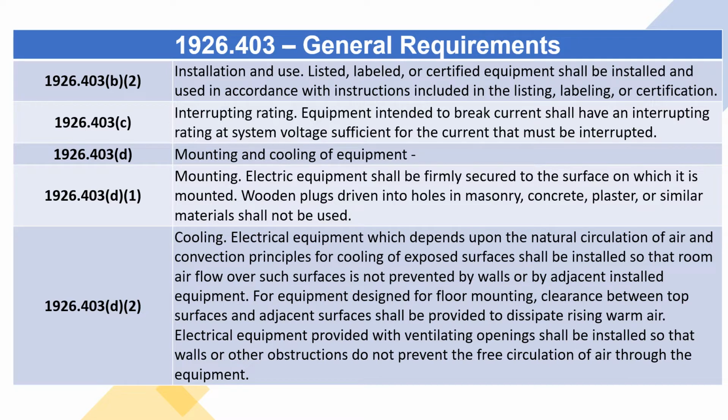1926.403(d) Mounting and cooling of equipment. (d)(1) Mounting. Electric equipment shall be firmly secured to the surface on which it is mounted. Wooden plugs driven into holes in masonry, concrete, plaster, or similar materials shall not be used.